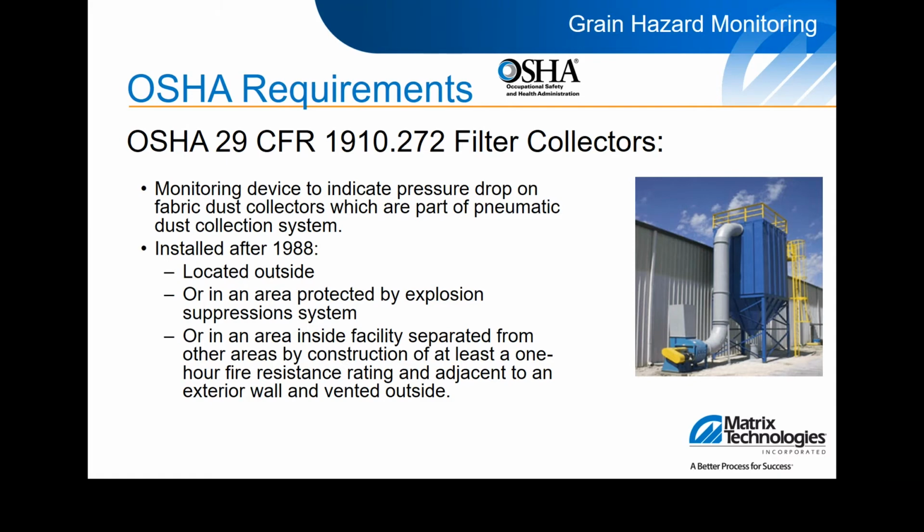There are several different methods of explosion suppression out there and available for dust collectors, including steam, chemical isolation, and also, more commonly, explosion venting.